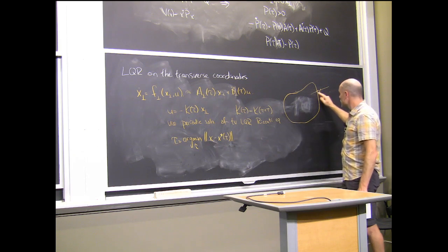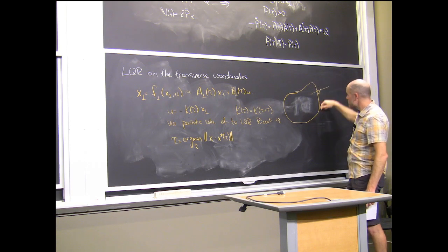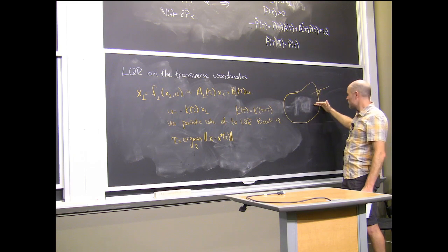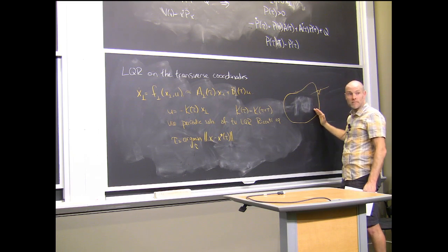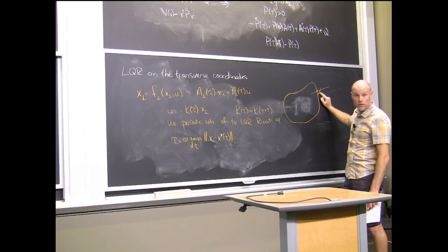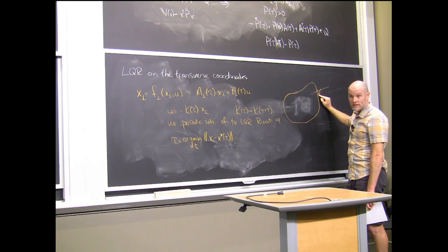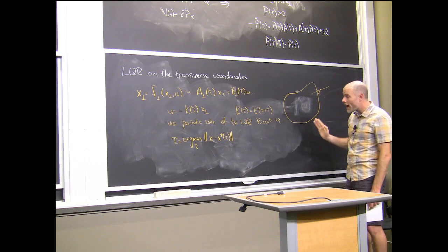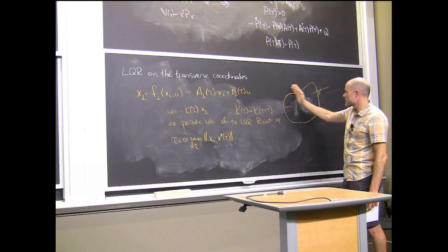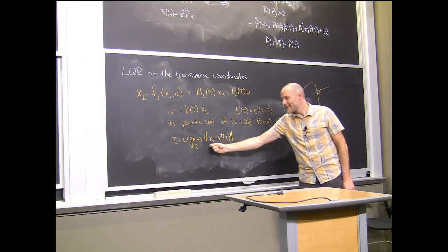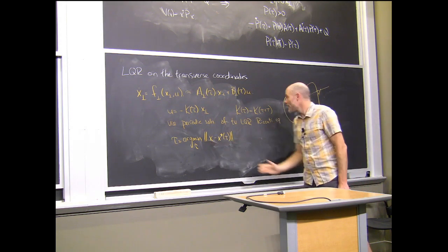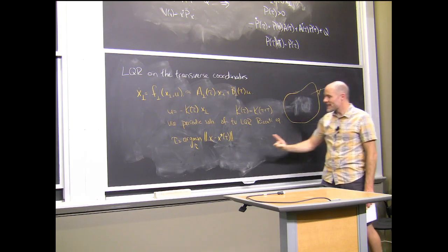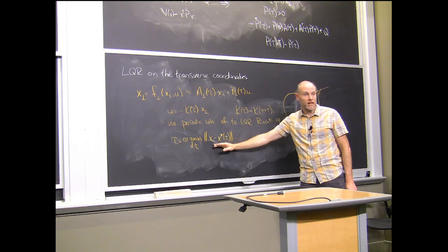That's a good controller in the sense that if you were to push me along the cycle, it's not going to try to slow down. If you push me or hold me back, it's not going to try to speed up. It's only stabilizing orbitally. It's not stabilizing in the full coordinates. You could try doing LQR on the full coordinate system and just do this in the full coordinates, and then choose a tau. But that's actually not guaranteed to be stable.